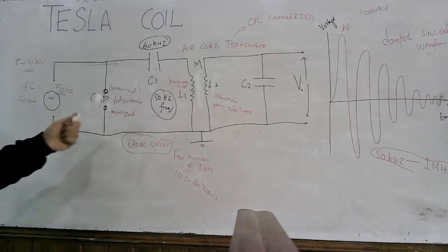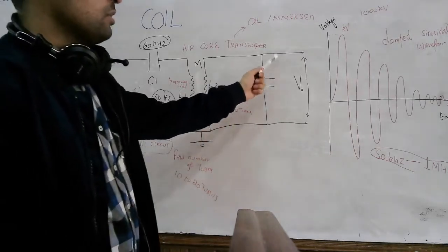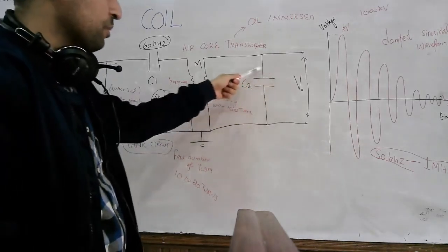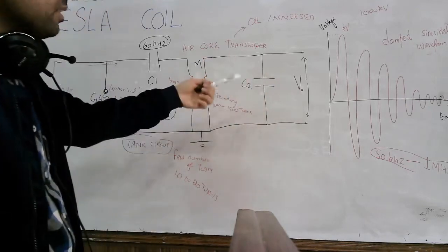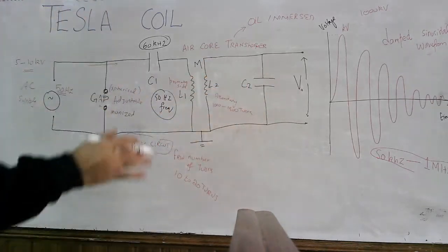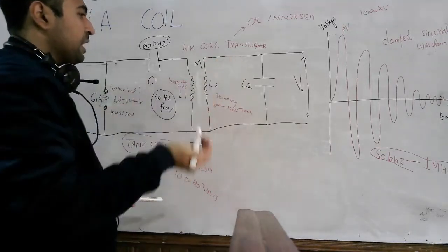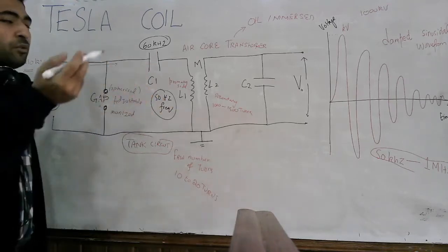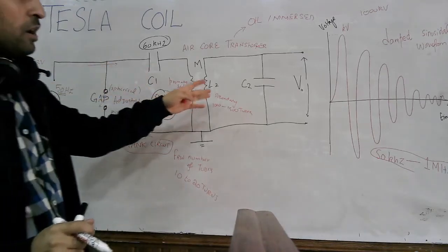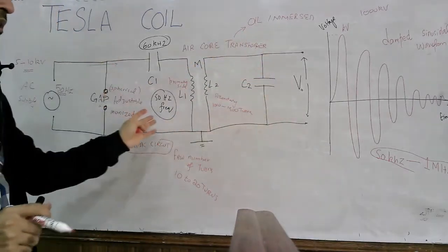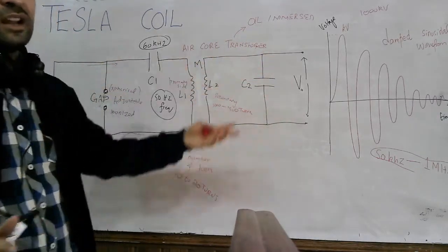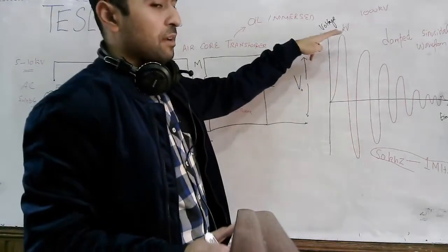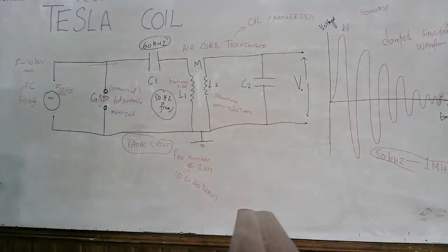And moreover, once you start getting the voltage here, this capacitor also heats up. The temperature of this capacitor rises, and because of these temperature effects, the values deviate from the values you have theoretically. So in some situations you are unable to reuse this experiment again and again for the desired level of voltage, because the resonant frequency changes. So this circuit has practical limitations.